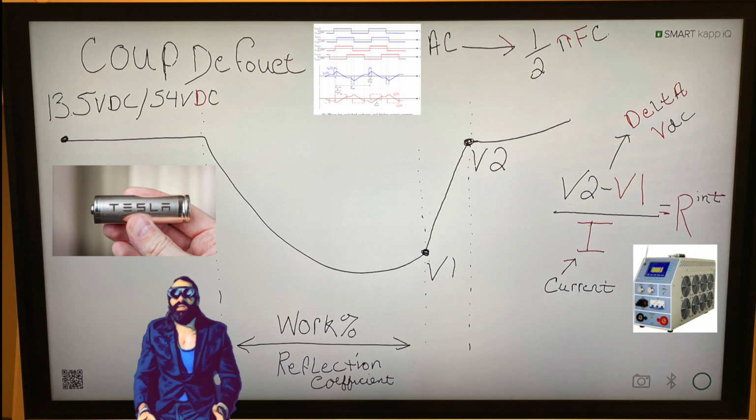I've always wondered this throughout the industry. Now we have so many different other types of monitoring technologies, and I will review that hopefully after this video, or I'll create a separate one based on AC impedance and AC conductance and so on and so forth, a few of those other variables, and they're very different than DC current, because if you're going to have a DC system, a 540 volt DC bus on a 750 kVA UPS or 1 megawatt 3-phase UPS, you need to understand how to test this effectively.